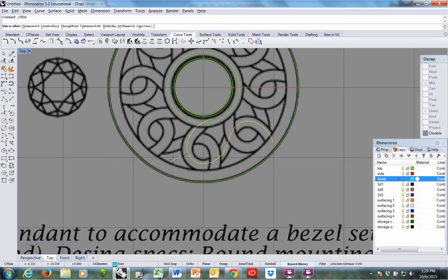Right now it's set to 0.9, so if I put that on both sides it's 1.8, and that's a little heavy, I think. So I'm going to make it 1.7 total. 1.7 would be 0.85, so I'll type in 0.85. That offsets 0.85 on each side,